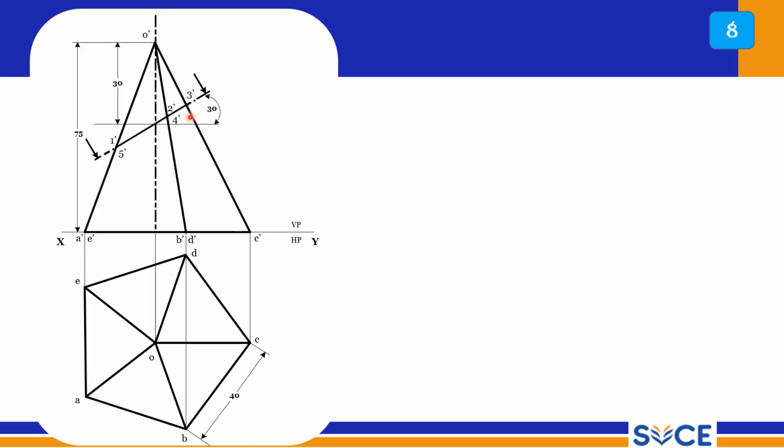2 and 4 should be projected onto the true length line, 1 and 5 should be projected onto the true length line. You have to measure the true length along this OE line. For all the points you have to measure on the OE line, that gives you the true length. So using that true length you have to do the development. This is a very important point you should never miss. So draw the development. The true length of this slant edge OE, I am getting 79 mm.